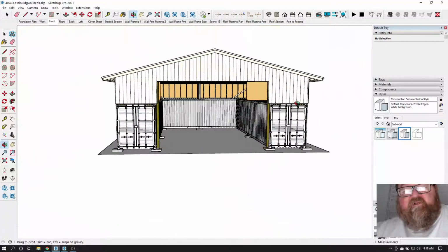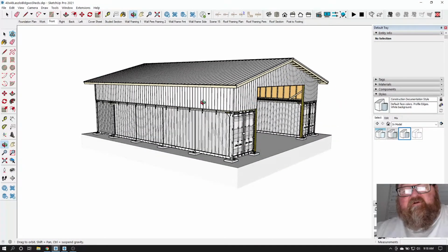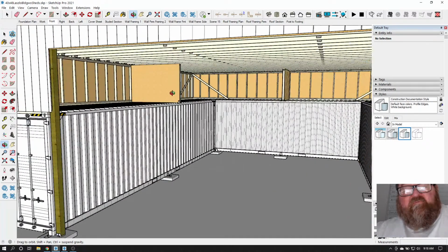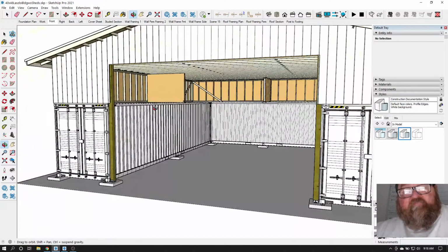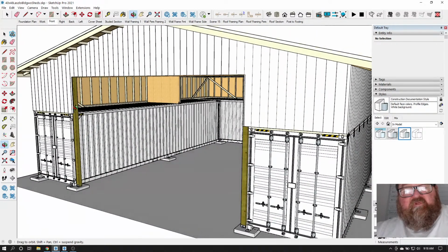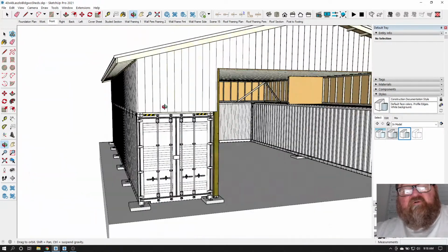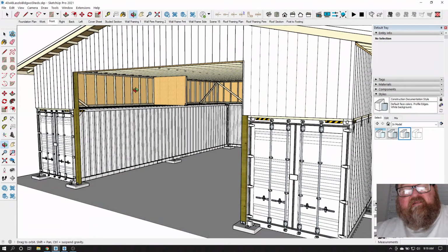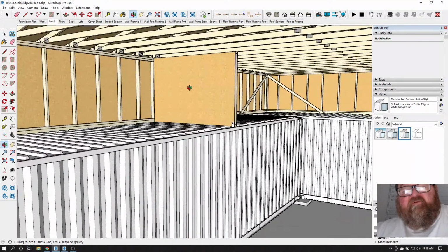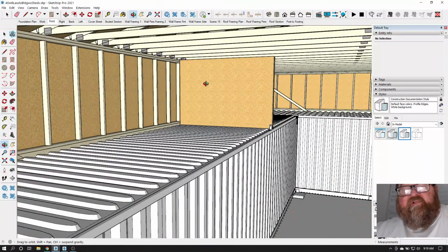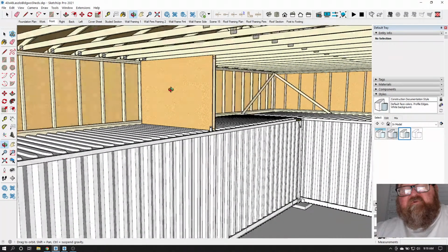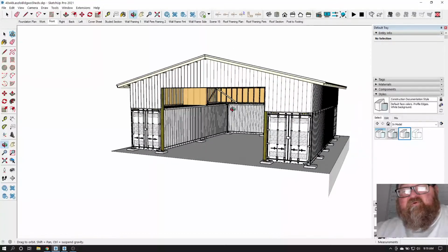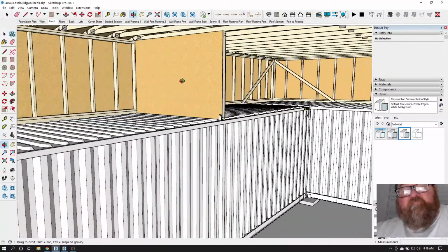But going here, we have these shear walls, and these shear walls are actually required by code. You can imagine this long wall is unbraced if you do away with the shear wall. In a home, it's rare that you would have a 40-foot long wall without a bedroom wall or a living room or a bathroom wall intersecting it at a 90 degree, perpendicular to it. And those walls in your house help brace the other walls. They all work together. Well, in a big open building like this, you don't have any shear walls, so this is an easy way to come up with one.